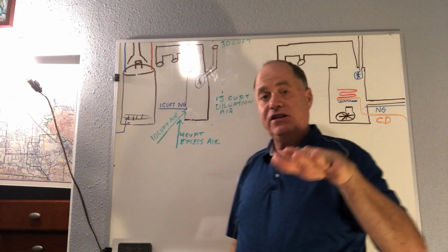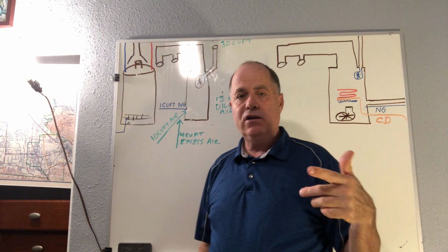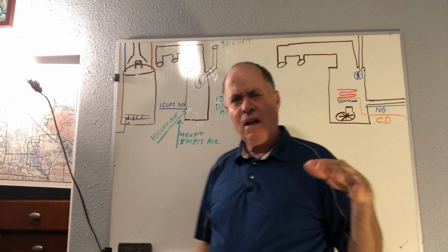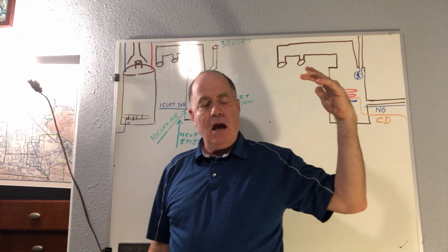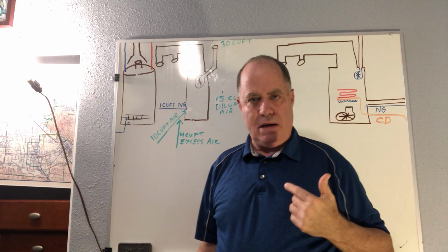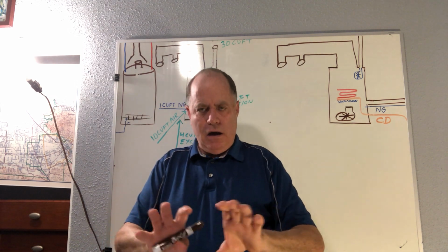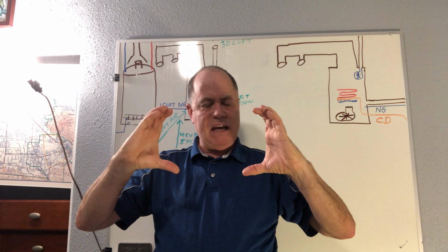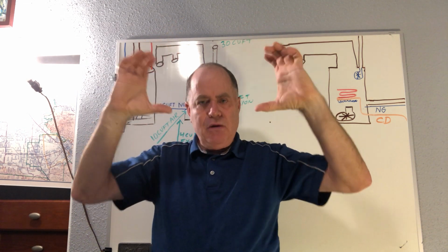Garages are another place where you'll see a lot of heating appliances, hot water heaters, furnaces, right? Also, you'll notice in garages you tend to have that upper and lower opening concept, where you'll see these screens down at the bottom of the garage, little openings about this big, maybe 8 of them, with screens, and then you look up near the top and you have another one.